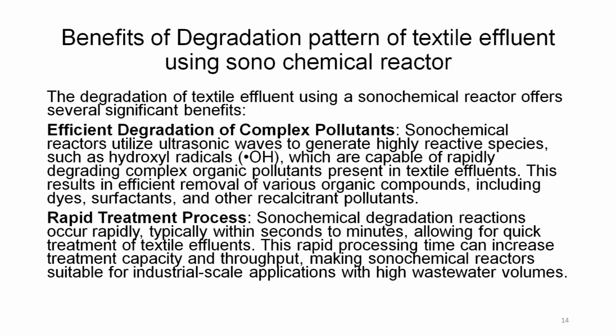Sonochemical reactors utilize ultrasonic waves to generate highly reactive species such as hydroxyl radicals, which are capable of rapidly degrading complex organic pollutants present in the textile effluents. This results in efficient removal of various organic compounds including dyes, surfactants and other recalcitrant pollutants.